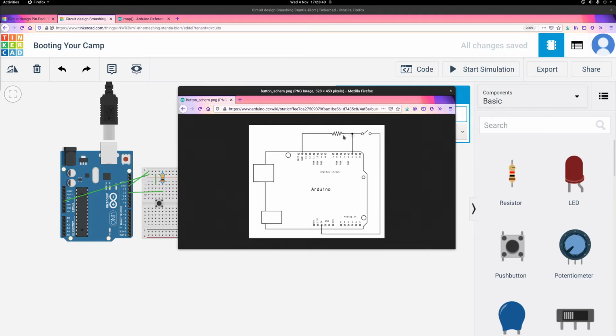What we've done now is added a resistor to it that's pulling it down to ground. So when this switch is not pressed, the circuit just looks like this section here. So you don't see any of this stuff. It's just this bit when the circuit is open, when the button is not pressed. So obviously then, you just have your pin 2 connected to ground. So it's going to look like it's connected to ground. You'll get a 0 value, a low voltage.